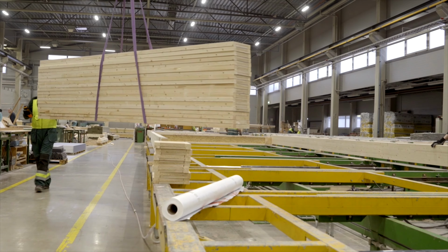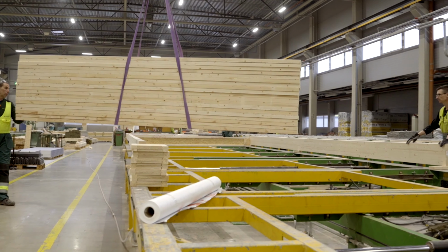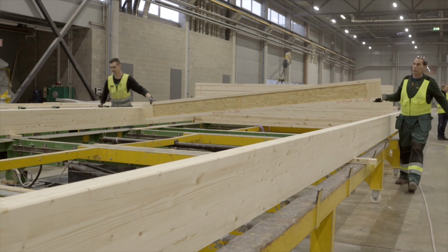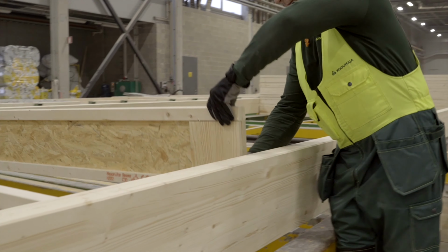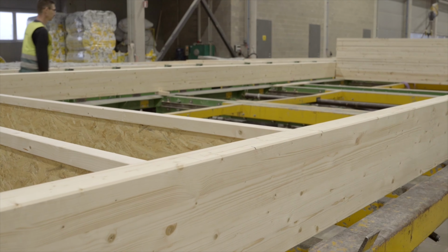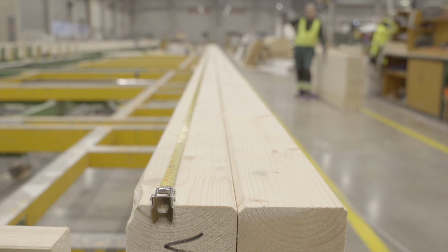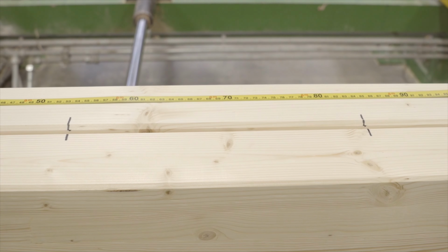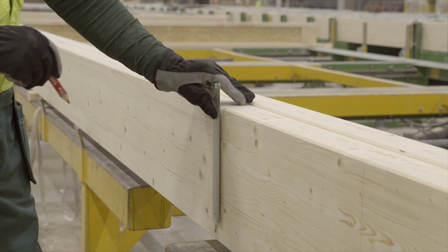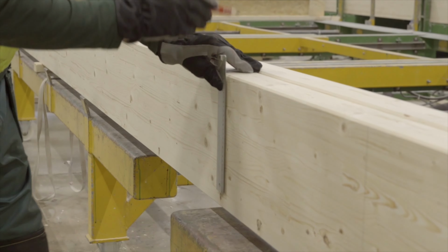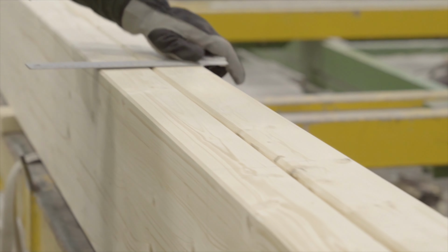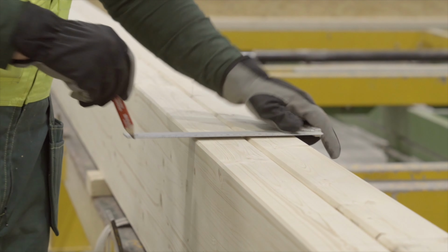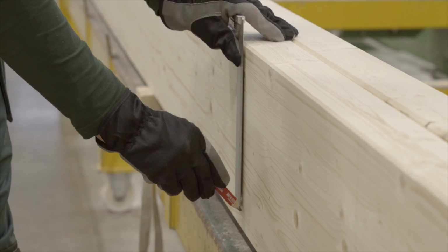For assembling the floor framework, both solid wood beams and wood-based I-beams are used. Hybrid beams, where the beams are tied together with a metal framework, are less common. If there are no machine-tapped pockets for intermediate beams on the edge beams, the locations of the intermediate beams must be marked on the edge beams before assembling the framework. This should be done for two beams at a time, using a sufficiently long measuring tape and a square.